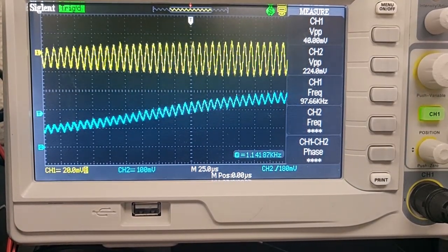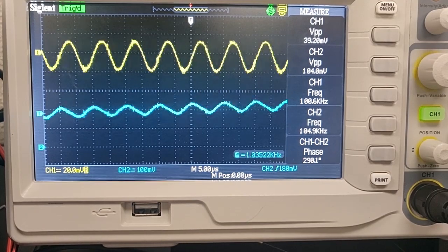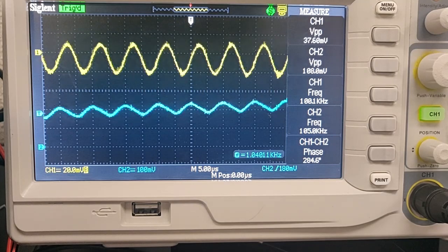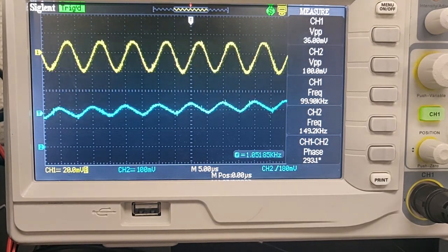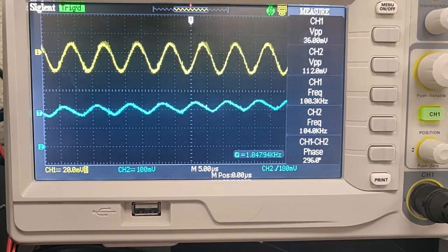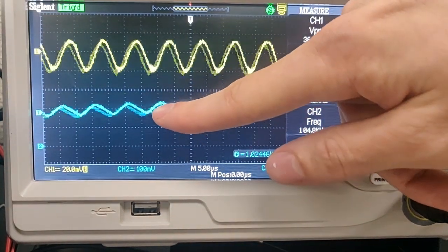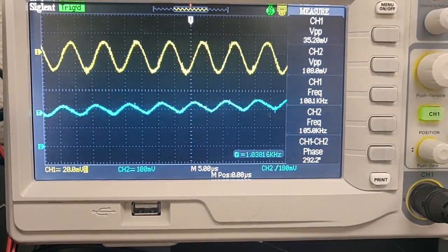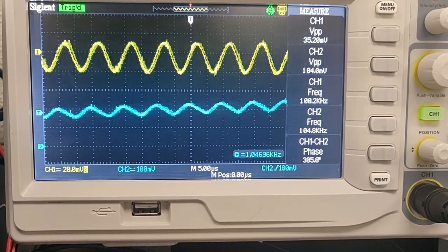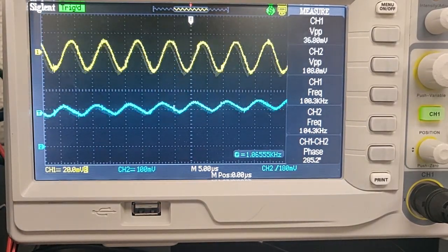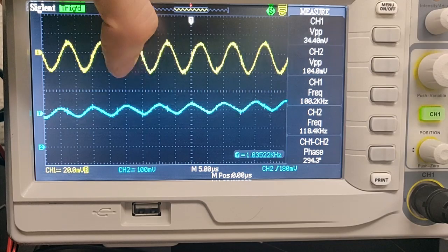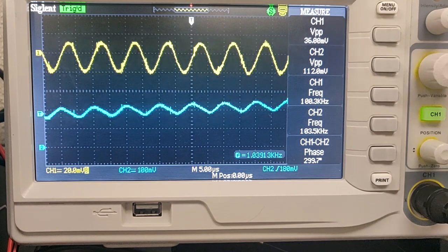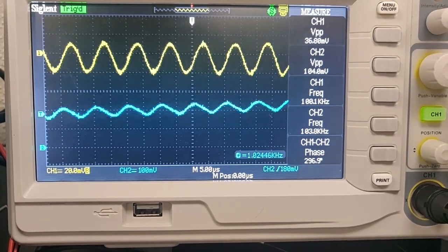We can start to see that our demodulated signal is still actually this carrier wave. It's the same frequency as our carrier wave. Just really, if we look at our scale, it's 5 microseconds for one box. So our wave is roughly 2, so that corresponds to a frequency of 100,000 hertz, and so it's still kind of hidden in there.